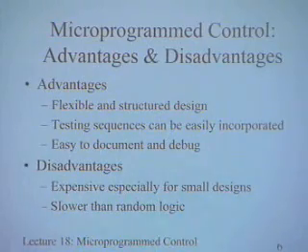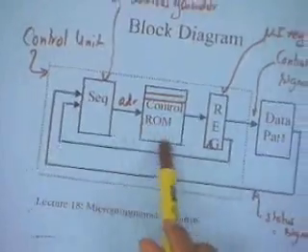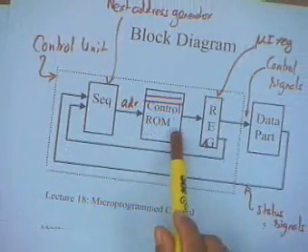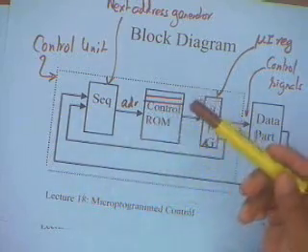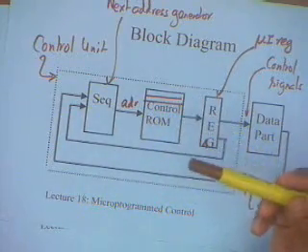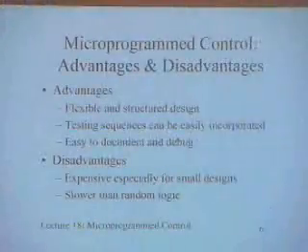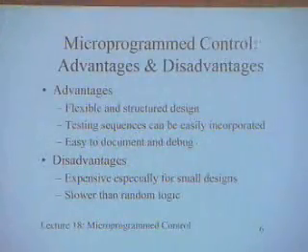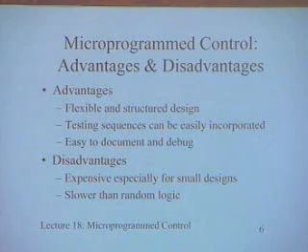In case of microprogrammed control design, it may only include that I may have to program a few more instructions in the control ROM, by which I can excite the paths, I can actually activate the paths which are required for performing the testing, and I can get my testing done. Whereas in a random logic design, it may involve redesigning completely different circuits, or if you want to make it optimal with the existing circuits, you might have to redesign the existing designs also.